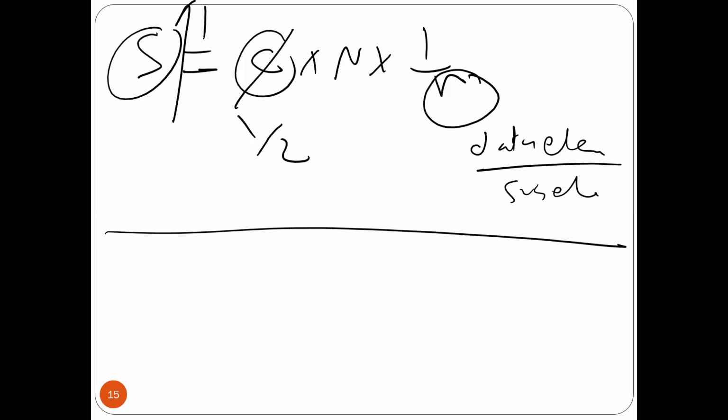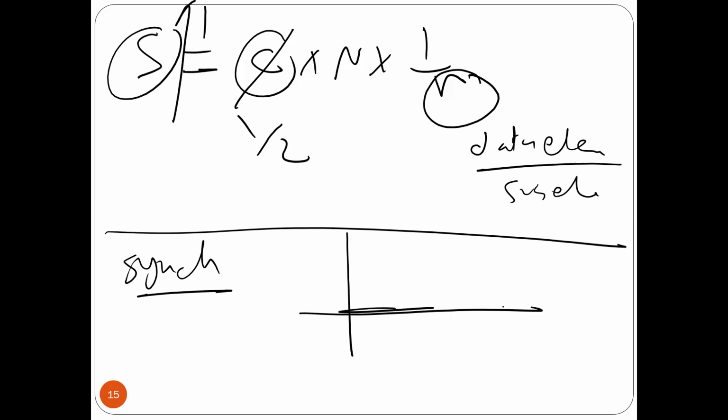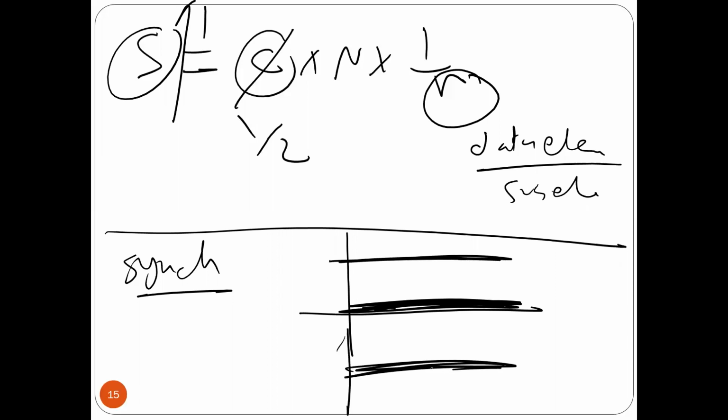Number two, for synchronization, if you look at the voltage for any pattern, can the voltage be fixed at zero for some time, or fixed positive for some time, or fixed negative for some time? If this is the case, yes, we have a synchronization problem. We need to introduce transitions to help the receiver resynchronize.